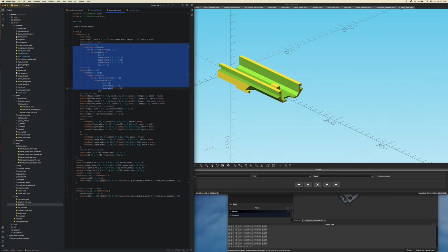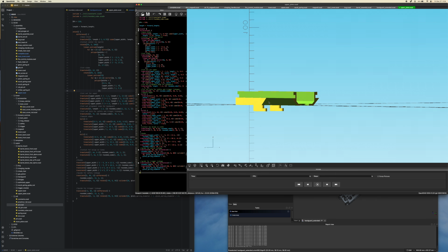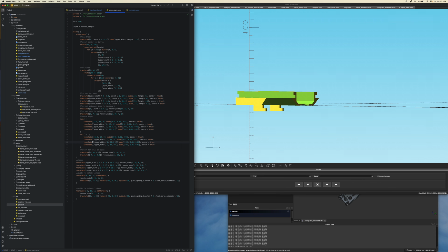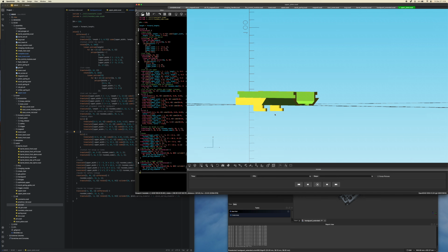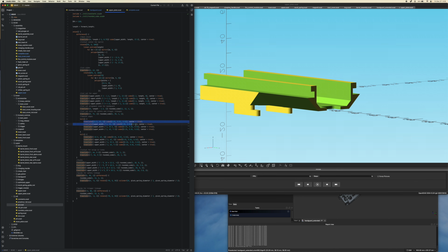I'm doing extrusion over here, but the only difference is there is one function in here that wasn't present in the last one that I think is extremely useful, and that is the hull. A hull basically means just wrap everything within it. Let's say it's shrink wrapped, right?